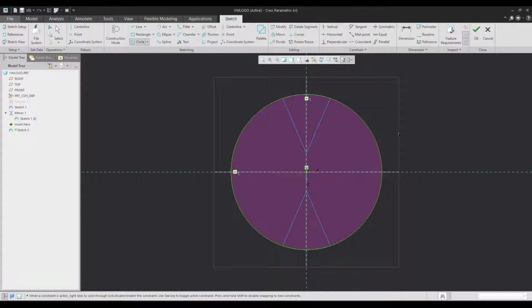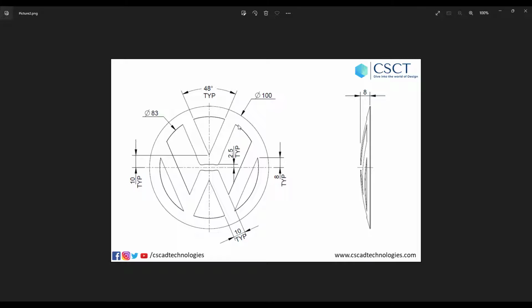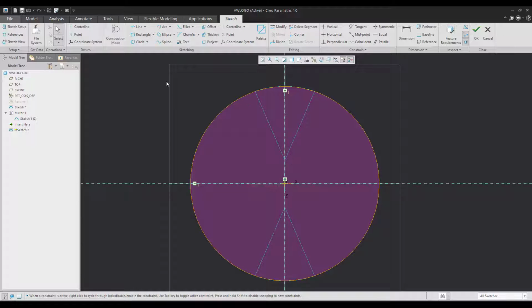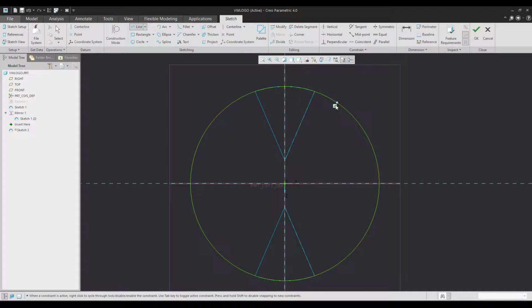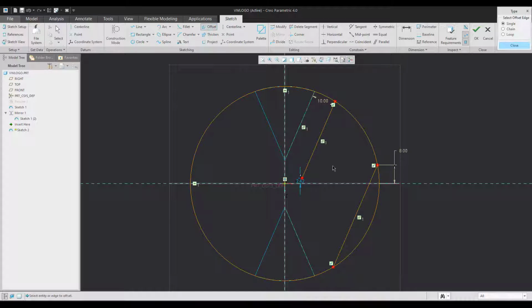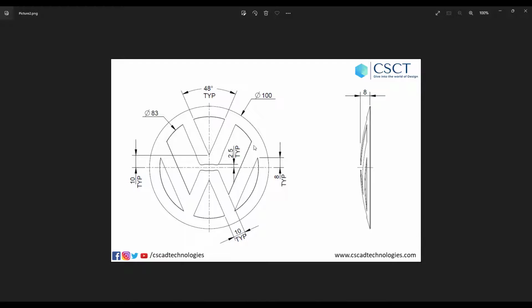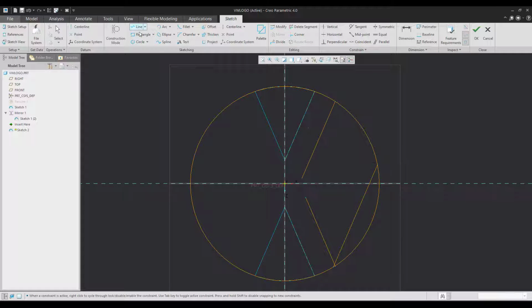Make a circle. Now let me begin by making these features. I have a line. Everything is maintaining 10 and maintaining parallelism with this edge. So let me begin by doing that. It has to maintain parallelism and maintain 10. Perfect. Now there's also another line which is over here maintaining parallelism again, but the distance from this to the end point has been given as 8. I can offset this feature and give 10 because the lower part is given as 10 and this is meeting the lower part. Let me try to make another line and make it try to meet this by maintaining parallelism.